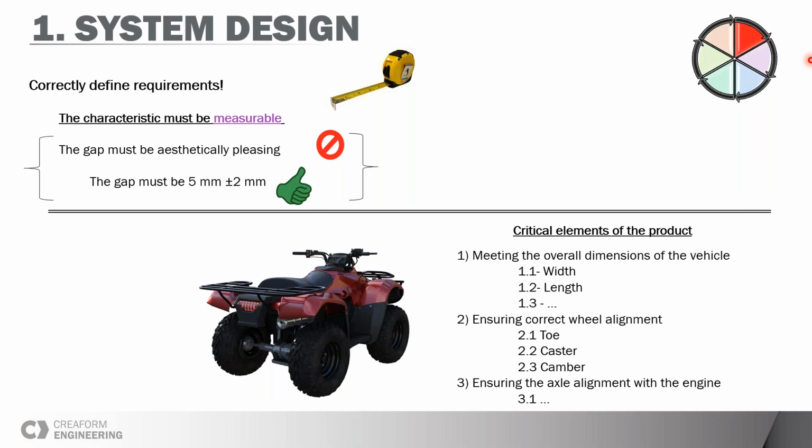Also, I think the question relates to doing it the reverse way: getting all the parts, making the statistical study, and saying this is the tolerance you should put. Functional requirements, let's say for an aerospace jet engine, could be very tight and very important. Once your engine starts turning, you have to make sure there's no gap between certain compression blades and the outside casing. It's a functional requirement. If you have a gap there, you're done. The engine won't be running and it's dangerous.